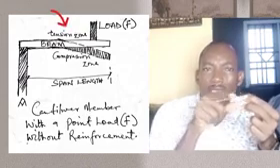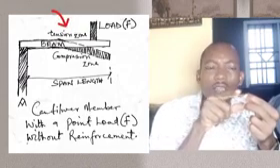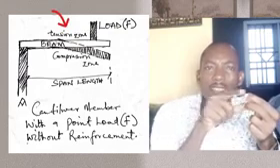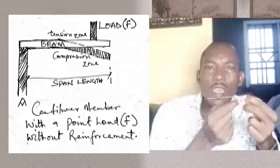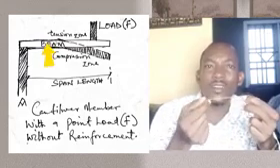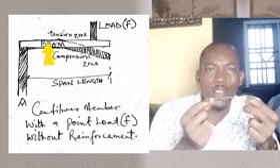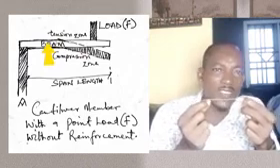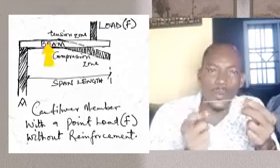So in order to protect this area from pulling out or from getting bad, rod needs to be provided at the top here. All right, then at the bottom here, where you have compression, the compressive stresses are developed here, you can provide less rod at the bottom of that beam.